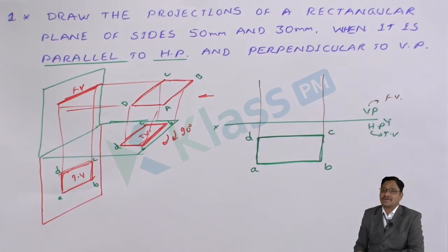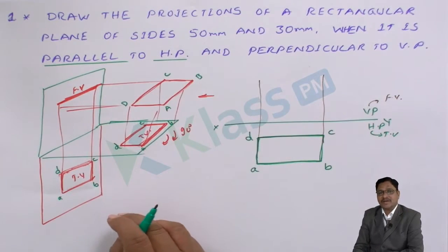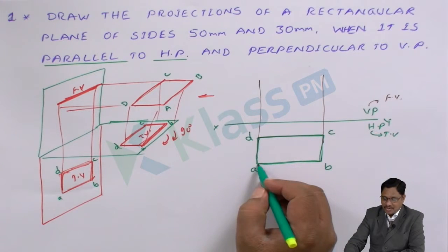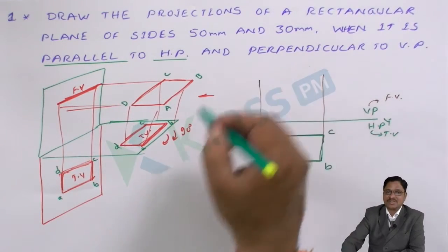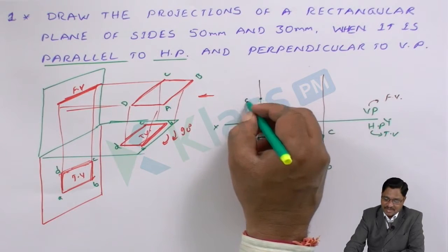Front view shows the details of the horizontal plane. Is there any distance above given? In this problem it is not given. Whenever it is not given, we can choose any convenient length. So now considering here, the top view of the A point is here. In the same A point, the projection on this is somewhere A dash. Since it is not given, we can assume any point as A dash.